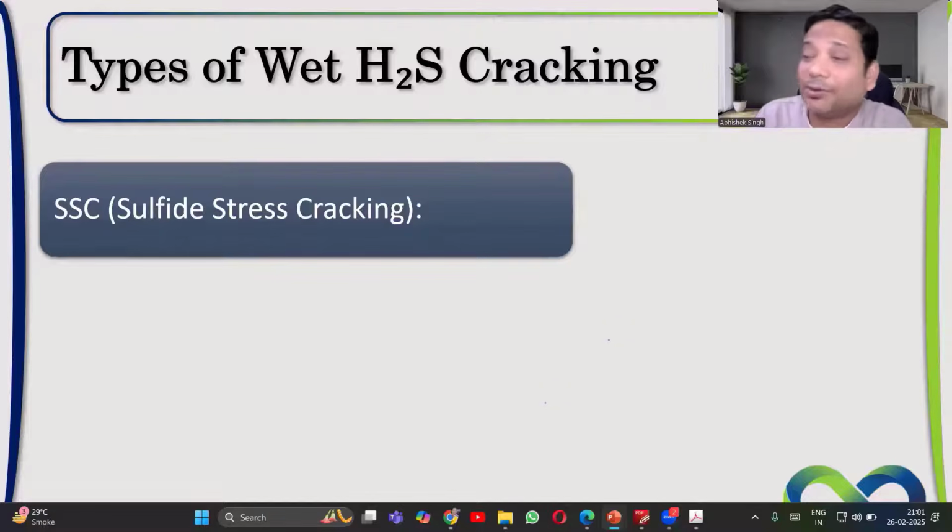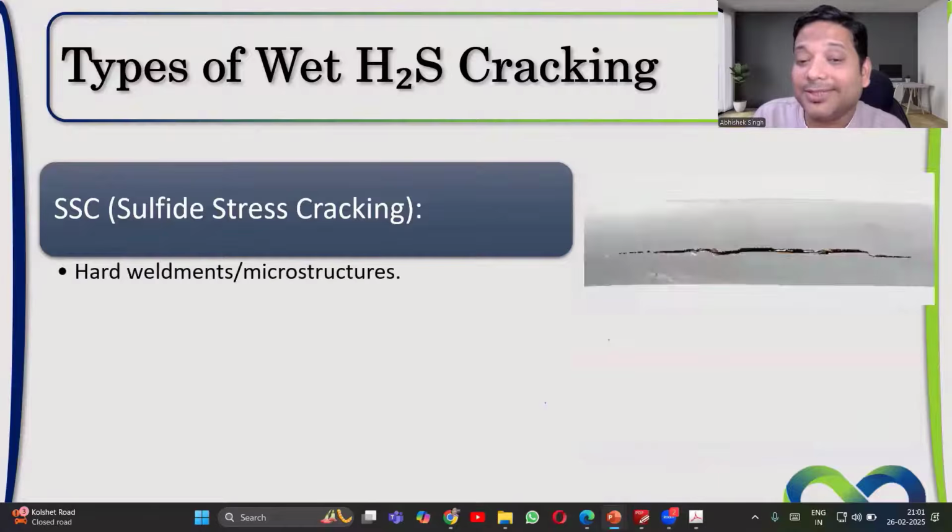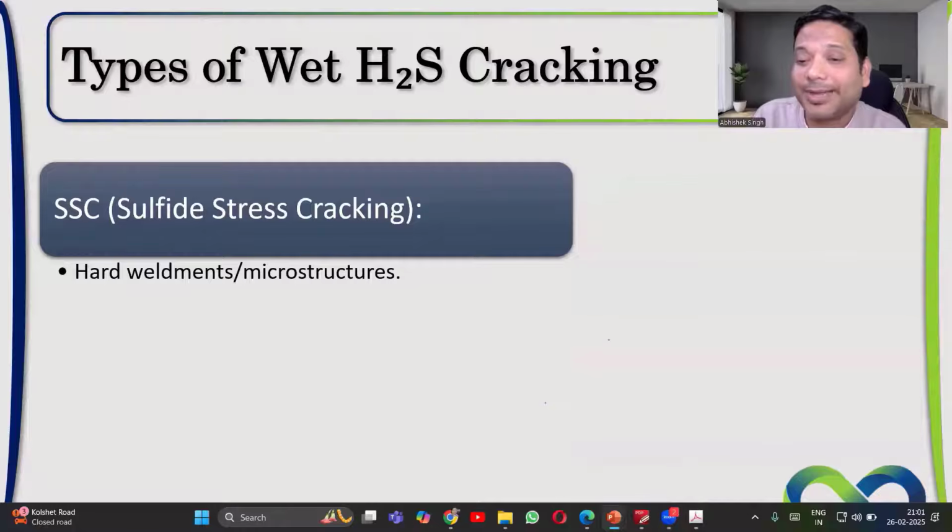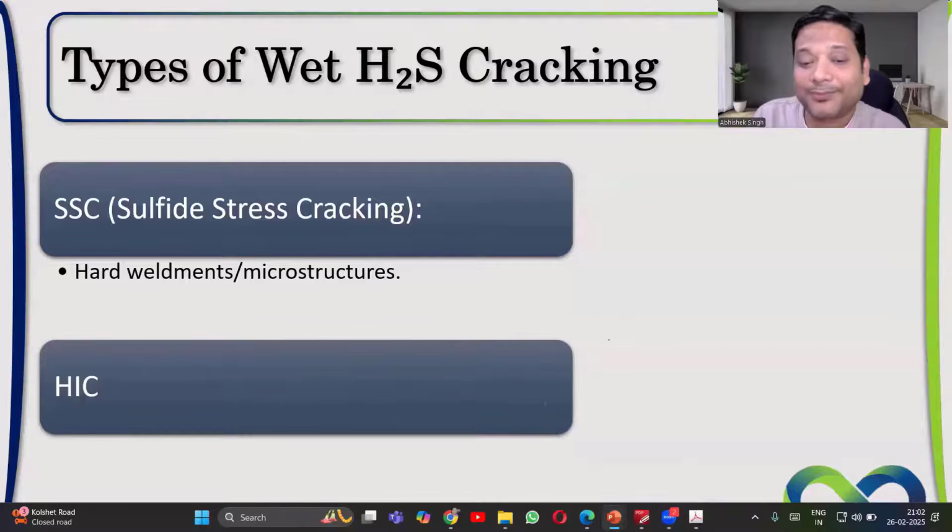Even 0175 mentions that it is still being developed. The phenomenon is not widely known, and it happens in very few equipment. So that's the reason I've kept two things, and among these two I'll try to clear up the difference between SSC and HIC. SOHIC is also similar to HIC, with a small difference.